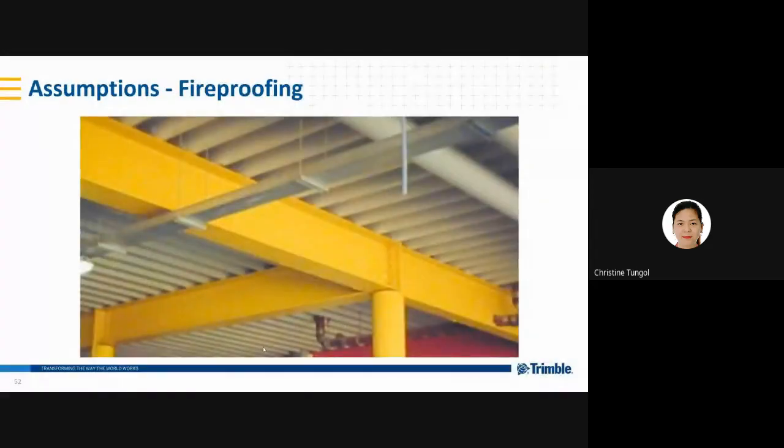Fireproofing is applicable for all design codes available in Tekla Structural Designer. Fire protection property is considered in the loading and analysis and is applicable for all 1D members irrespective of their characteristics, except for analysis elements, Delta beam, and Fabsec beam. Note that although the user gets the facility to fire protect any member they want, it is not expected that fireproofing be applied on concrete members, but on enclosed members, which will be influential to the open structure wind loading.